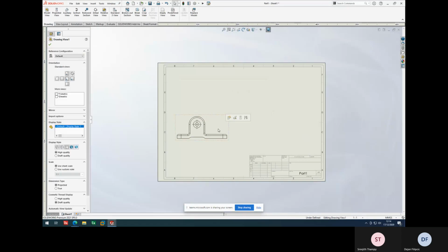So once I bring in a view, I have different options here. Configuration is like I have told us earlier, for the same component we can have different configurations. For example, you are having a model of an M10 bolt. The M10 bolt can be of 100 mm, it can be of 80 mm, it can be of 120 mm. You don't need to make these multiple configurations in different models. Just by changing shapes, you can save it as different configurations. We'll learn about configurations in detail.